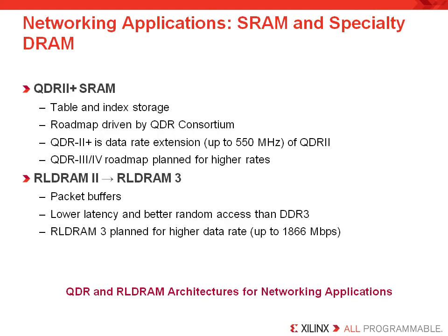These are a couple of the memory technologies that are important. QDR2+ is the latest evolution of the quad data rate SRAM. QDR is different from DDR. It is a static SRAM, is very fast, and has a relatively big memory cell. SRAMs are lower in density than DRAMs.